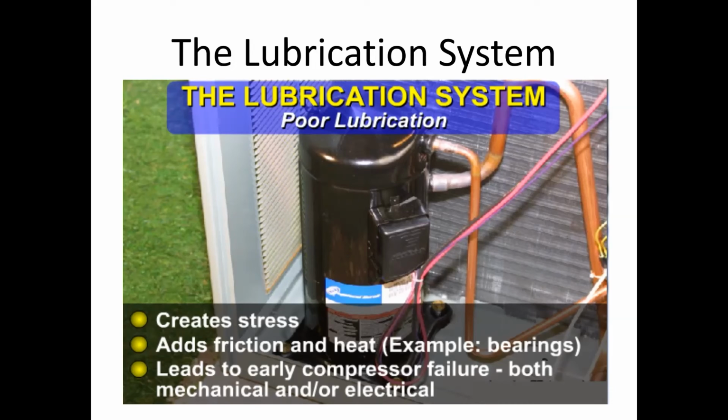You'll start to wear the bearings. You'll start to wear the scroll plates or the scroll set. Those things can both lead to early failure. Pulling liquid refrigerant back into your compressor can also displace the oil that it's pumping and cause it to not lubricate properly either.